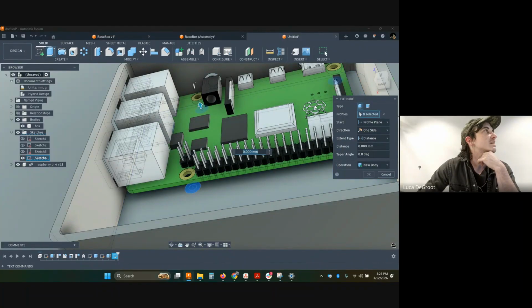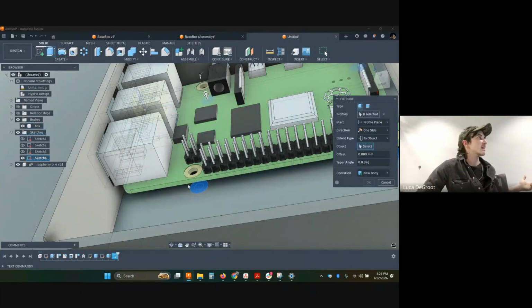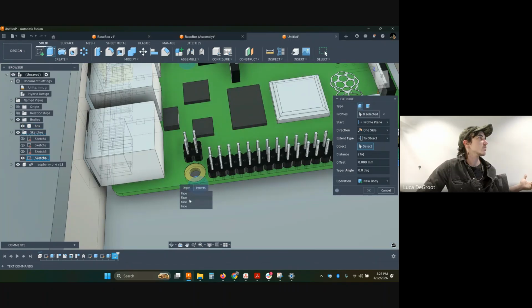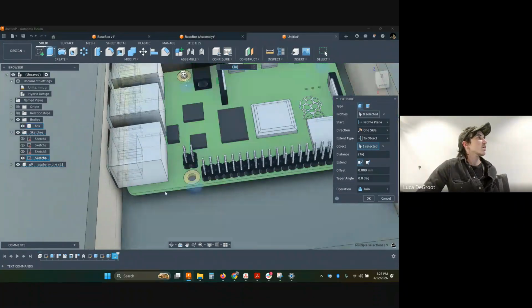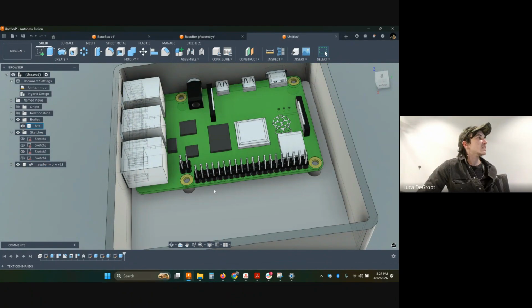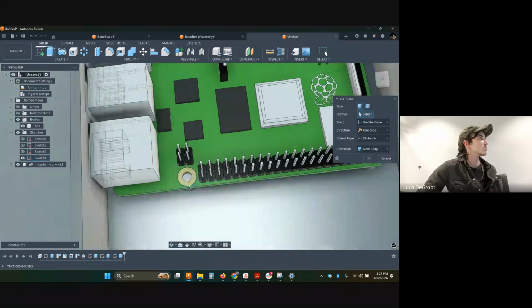So when I do this projection, one of the sketch extrusion options is extent type. I can do To Object. So I can select maybe the bottom face of this board. The lower face, I think, is that one. And so now this will hold that there. And then I'm going to do the same thing, go back and make my sketch visible.